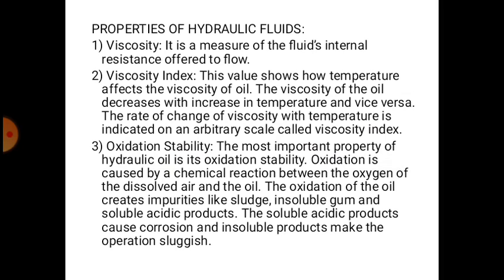Viscosity index. This value shows how temperature affects the viscosity of oil. The viscosity of the oil decreases with increase in temperature, and vice versa. The rate of change of viscosity with temperature is indicated on an arbitrary scale called viscosity index.